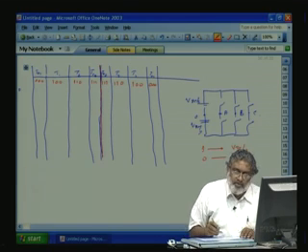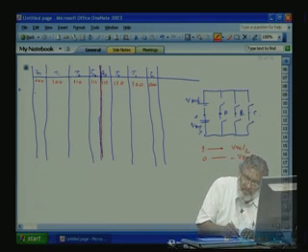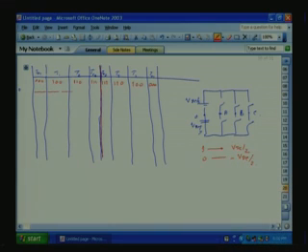So let us take for a general T1, T2 period how the pole voltage waveform for VA0 looks. We will draw VA0 with red color. During the T0 period, VA will be negative, so the pole voltage during this period is negative.